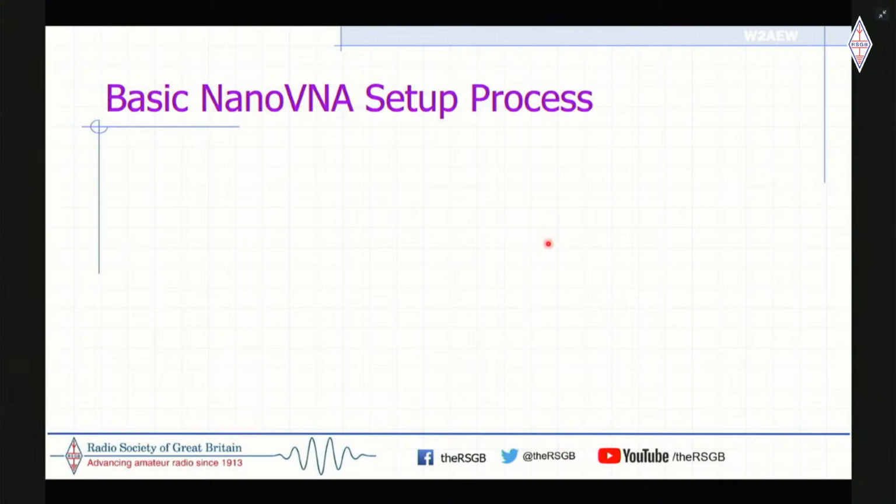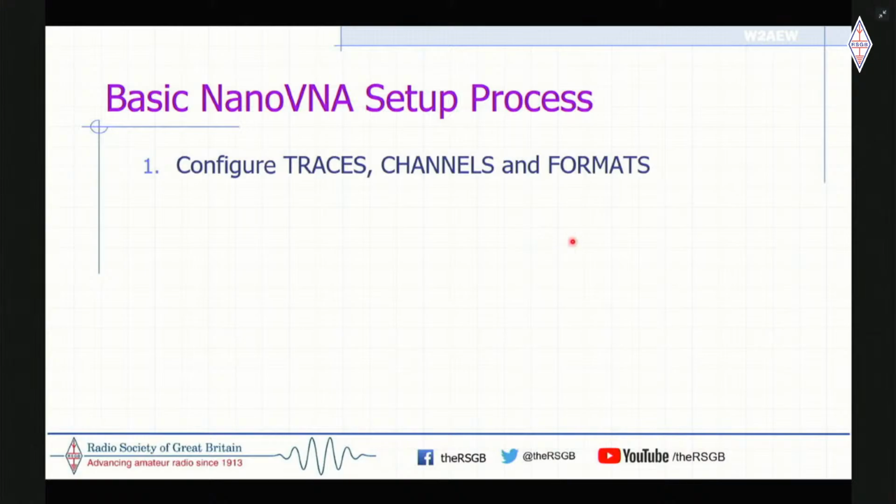So here, how do we set up the NanoVNA to actually go do something? Typically you are going to first configure the traces, what channels you want those traces on and what format you want. Okay, maybe I want a channel to show my S11 and another trace to show SWR. So I'd set both of those to channel 0 and set those two formats, log mag and SWR.